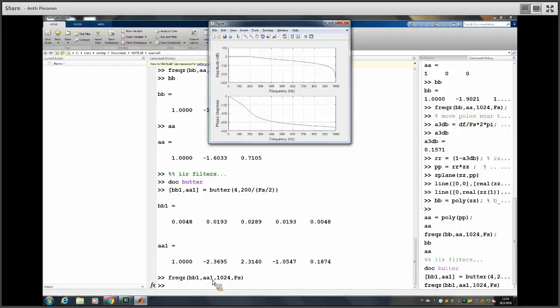How to actually find the correct design, since there's not too many things that you can change here. The passband ripple is usually defined by the application, how much you can tolerate.